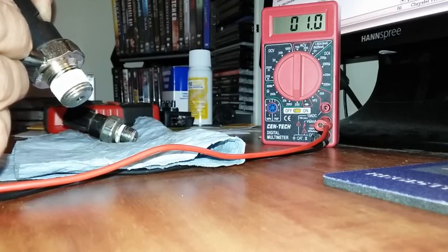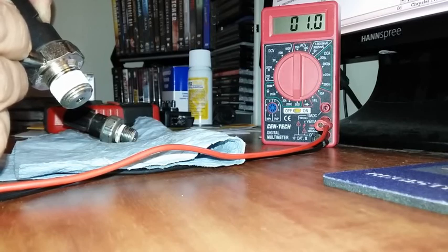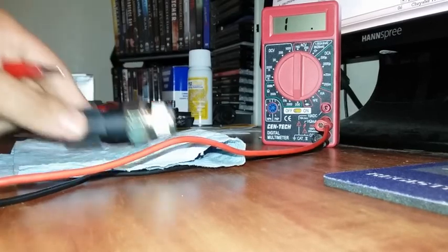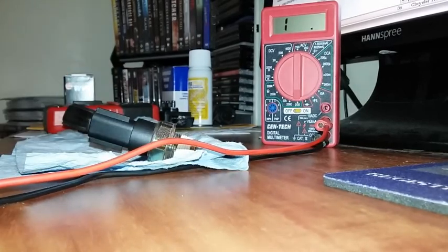So that means by installing this new pressure switch, this is going to solve the problem that this customer is having with an oil light coming on at random times, like I said earlier, during a cold startup or during a long drive, and on the second key cycle the light comes on.